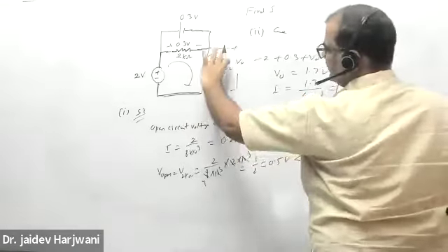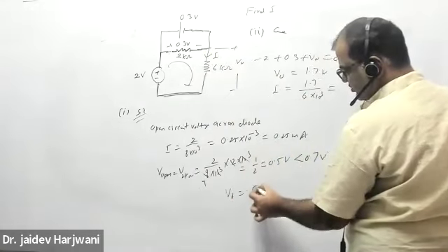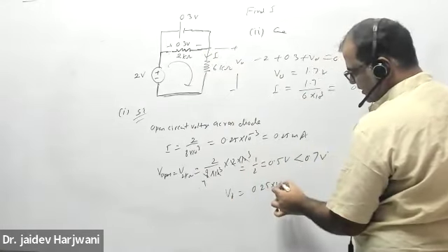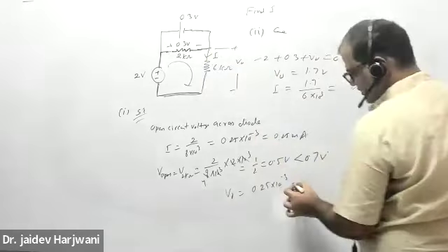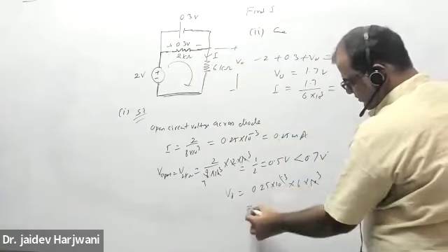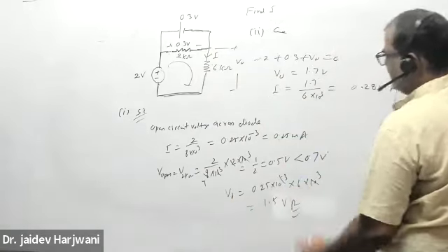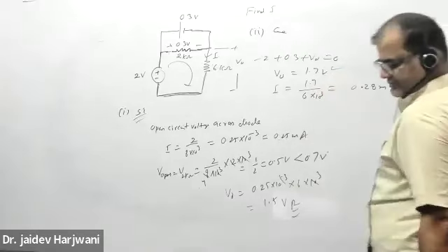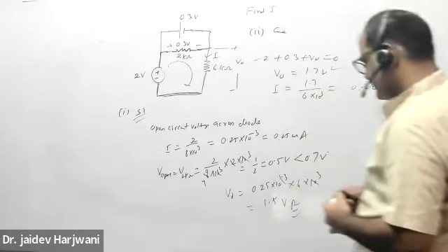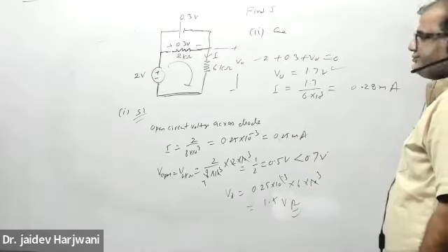And so here this is the V output. First case, what is the output here? Current was this one. So V output was first current. Current is this one, 0.25 milliampere into resistance of 6 kilo ohm. We can cancel out the kilo. Okay. So this becomes how much? 0.25 into 6 is 1.5 volt. And here the output is 1.7 volt. Correct? Yes or no? Yes, sir.